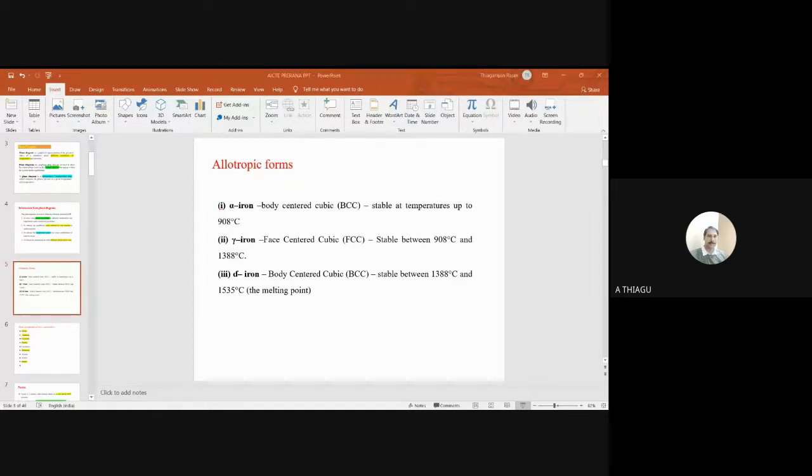Once you find this kind of structure, we can confirm it is austenite material. The hardness will be 200. Pearlite is nothing but a combination of ferrite and cementite, and the hardness will be 180. So this is the appearance. And sorbitic pearlite is the formation of ferrite and cementite, a group of materials gathered. Can you see? And this is a spherical shape. Once you confirm the spherical shape appearance, you can say it is a troostite form.